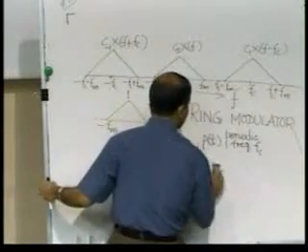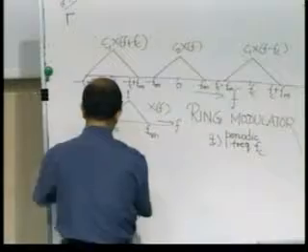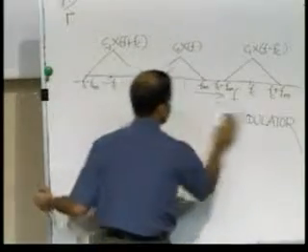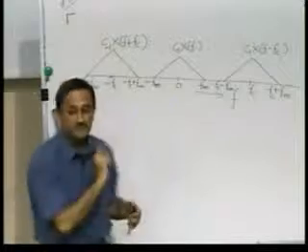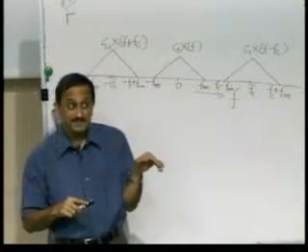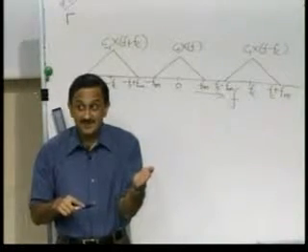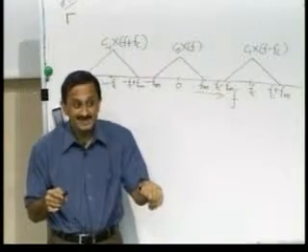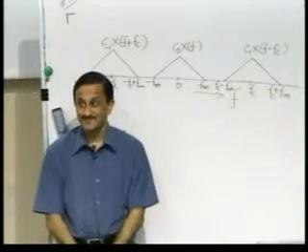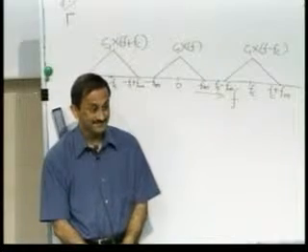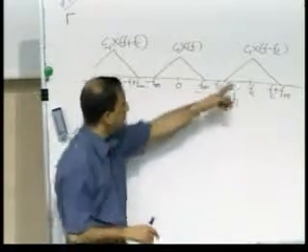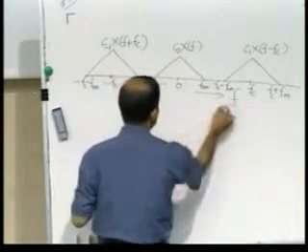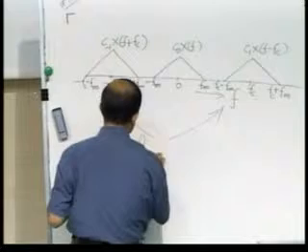In fact, I shall take this now from a converse perspective. Here, what have we done? We have made use of the fact that aliasing can take us from a low pass to a band pass signal, or we have been able to exploit aliasing to shift the band of the signal in question. Well, where are we using aliasing here? All these spectra are called aliased spectra.